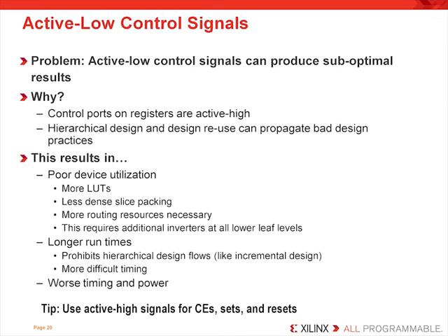Also keep in mind that if you're using an old design and targeting a newer FPGA, older devices sometimes had local inversions supported for all control signals. So when you are instantiating older components or designs into your new device, you should always reevaluate your control signals usage.